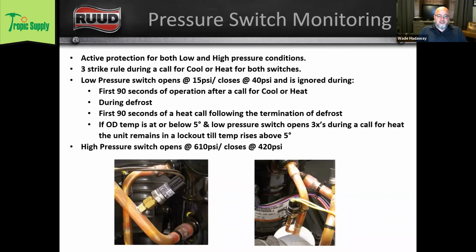And the high pressure switch opens at 610 and it closes at 420 psi. I don't expect you to remember any of this stuff. These specs are in the installation manual, and they're also in the service manual that you're going to get if you come to all 5 of these classes.